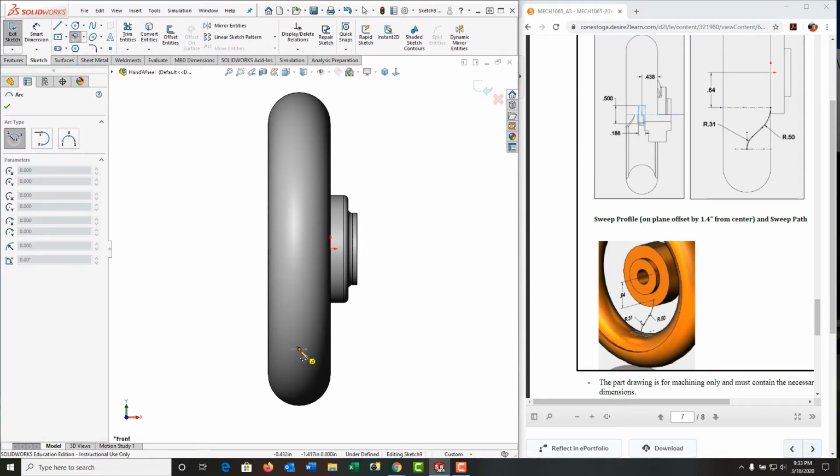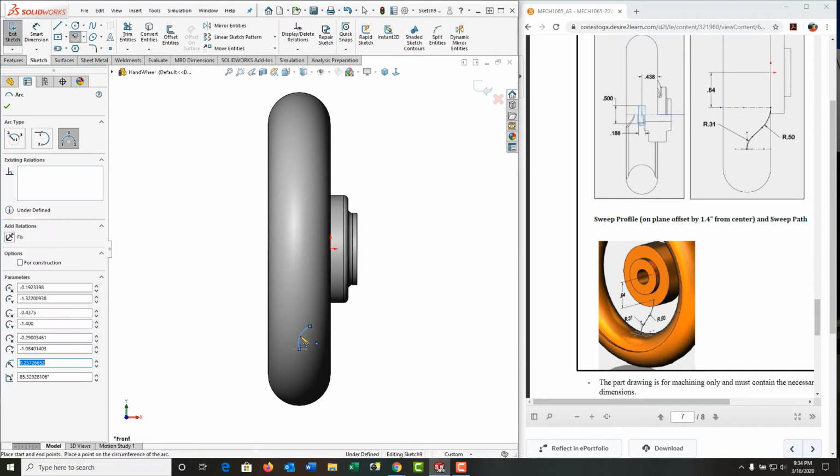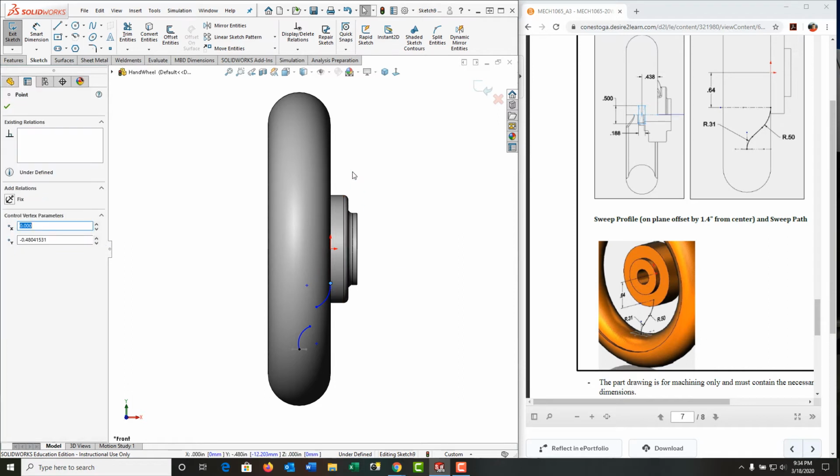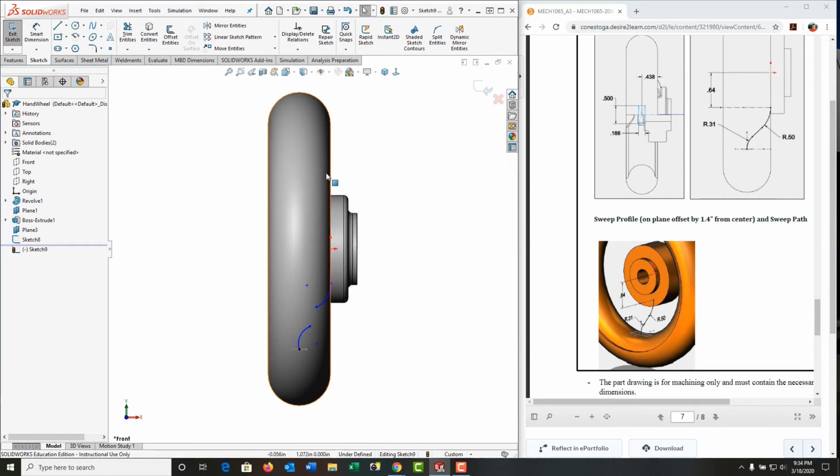And it's locked to the middle of this sketch. I'll grab that. I've got the wrong 3-point arc style. So I'll come up here and I'll fix it. And I'll start again. So from here to somewhere over here, I want that style of 3-point arc. And then somewhere up here to here, I'm going to have another 3-point arc. This point is on this edge.